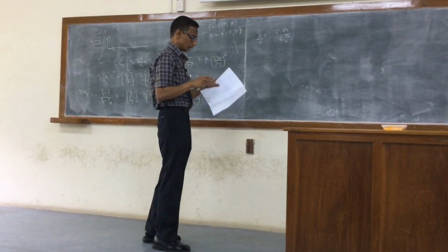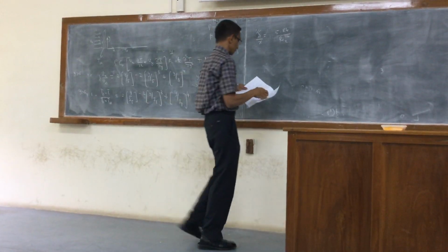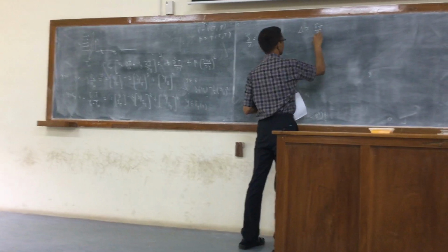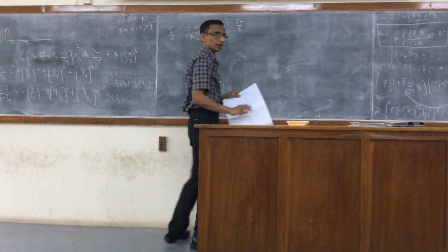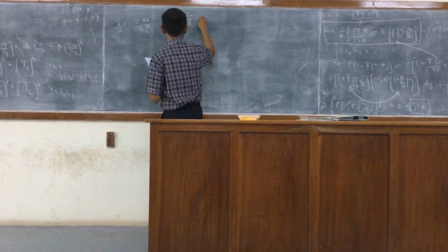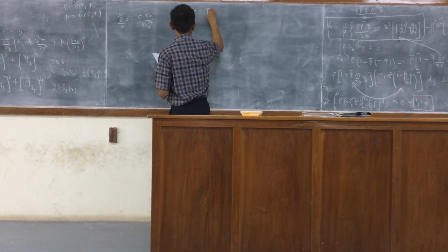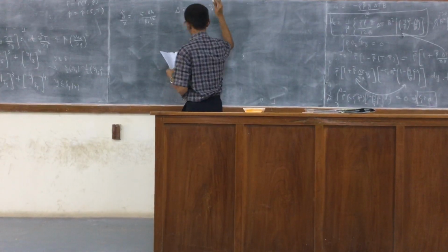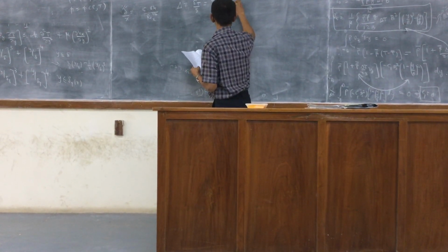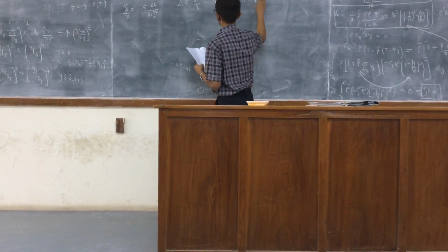It's all coming from an approximate analysis, and I'm not going to go into the details. And interestingly, the thermal boundary layer, again using an approximate scaling analysis, can be shown to be given by the Prandtl number to the power minus 1 over 3, for delta less than or equal to 1.